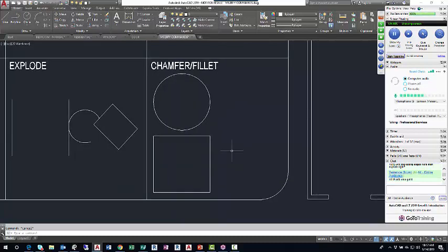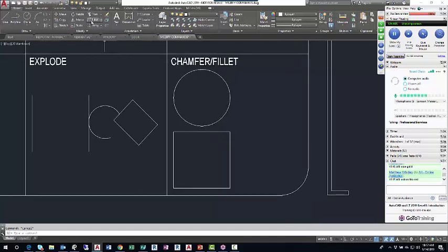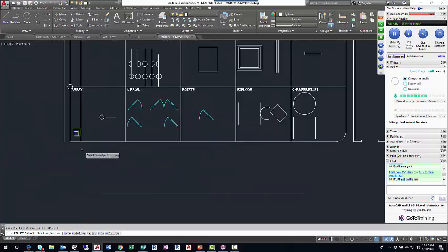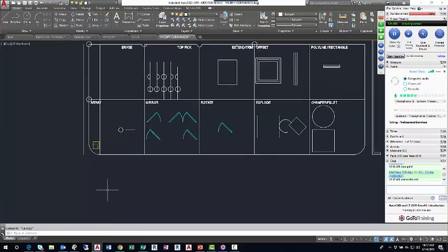So again, fillet is one of these commands we're going to use to refine a primitive shape. Not many more primitive shapes than the square, right? So I refined the square to a circle using fillet. I rounded those corners. In this drawing, fillet had a built-in radius of 1 foot. I clicked radius and I typed in 2 feet. But in most drawings, the fillet radius is set to 0, and it needs to be set to more than that.